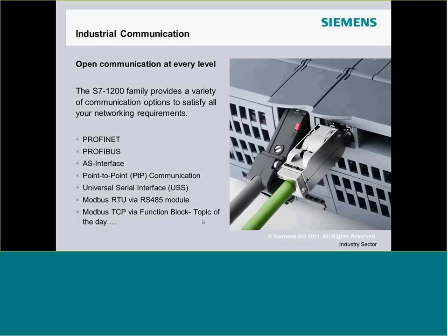The S7-1200 series PLC also has some additional features, such as a built-in web server and copy and know-how protection. Newer versions also have two Ethernet ports, which meets the need for an Ethernet switch. So we connect to the HMI from one port and the programming PC to the other directly via the PLC, without the need of a switch.